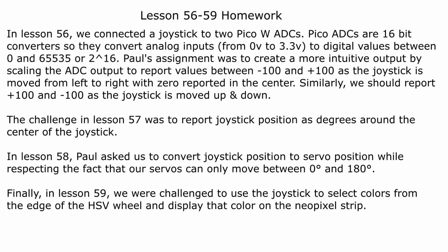The challenge in lesson 57 was to report joystick position as degrees around the center of the joystick. In lesson 58, Paul asked us to convert joystick position to servo position while respecting the fact that our servos can only move between 0 and 180 degrees. And finally, in lesson 59, we were challenged to use the joystick to select colors from the edge of the HSV wheel and display that color on the NeoPixel strip.